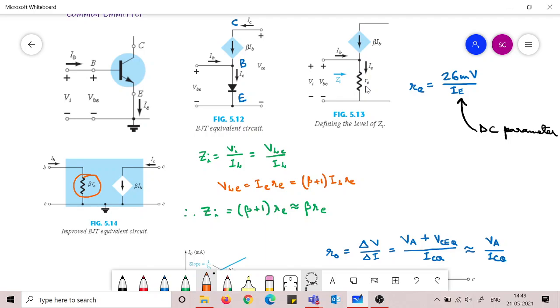Instead of drawing the transistor, which does not reveal any resistances or any information about what it is doing, we replace it with this AC equivalent model, and there the resistances and its behavior become very clear, and we are able to work with it simply in terms of circuit analysis that we are very used to doing.